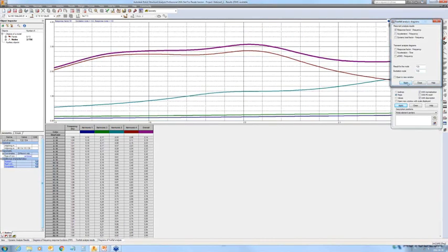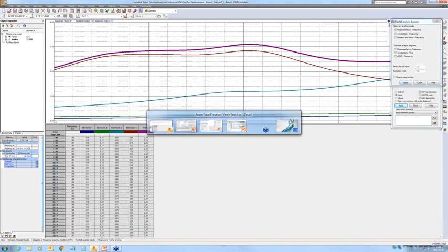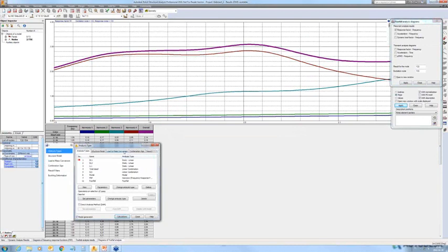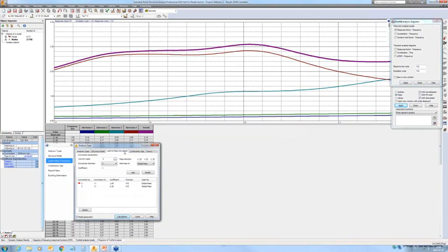And then, okay, let me go back to Robot, let me go back to the parameters of load to mass conversion. You remember that in one of the previous slides, the Eurocode value for live load conversion is 0.3, but this is considered a conservative value.